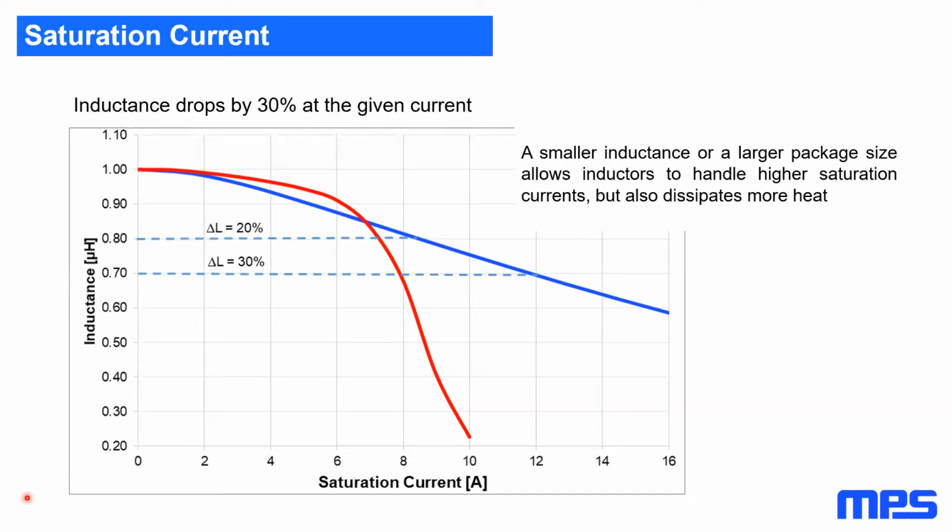Sven mentioned already that the inductance value is directly related to the relative permeability, which is temperature dependent. Ferrite drum cores have a comparably high relative permeability. That is why these inductors saturate earlier the higher the operating temperature gets. This causes challenges for wide temperature range operation. The composite molded types instead, on the right-hand side, have a low relative permeability core, showing a narrow deviation between the 25 and the 100 degree C curve. So in case a stable temperature behavior is necessary, the molded types are the way to go. Next, please.